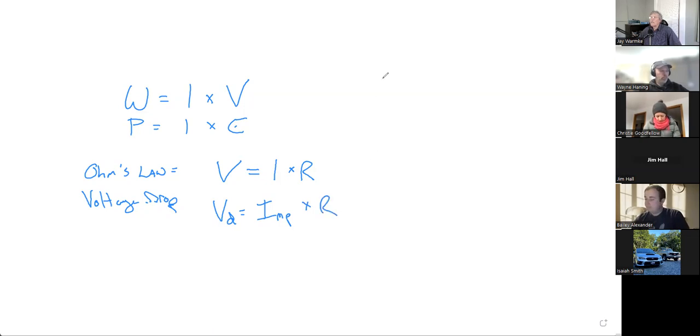But we get the resistance in the NEC in ohms per 1,000 feet. So now we've got to adjust for distance, so times twice the distance divided by 1,000 feet. And all that is taking the resistance that we're given.